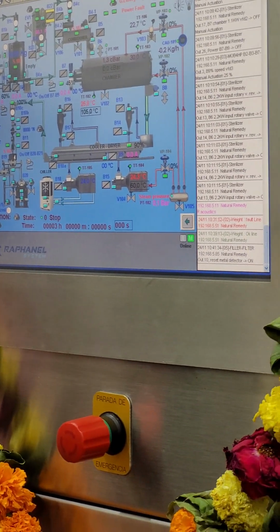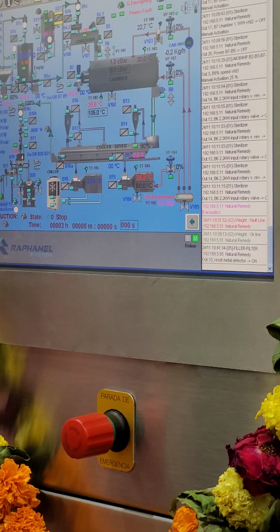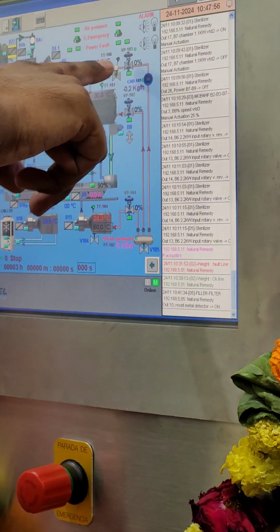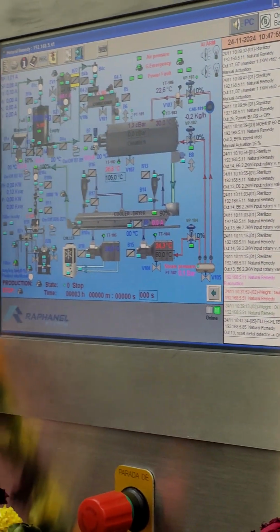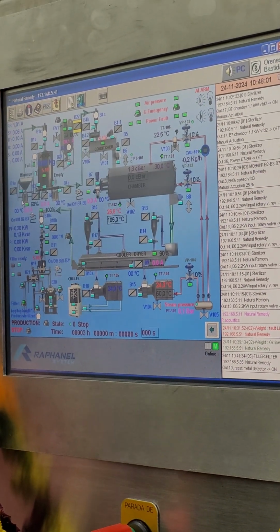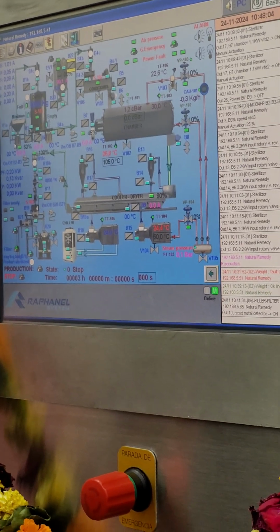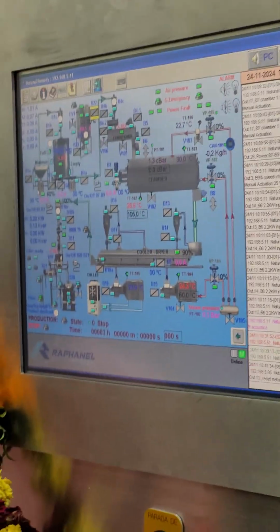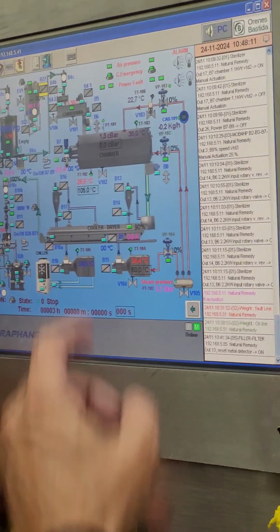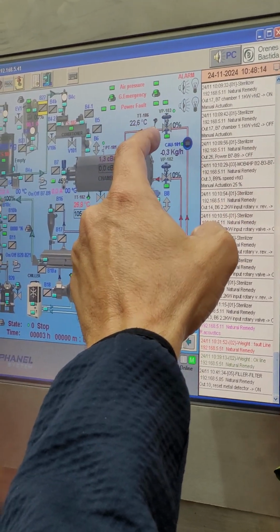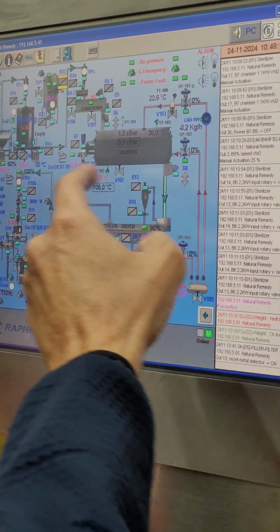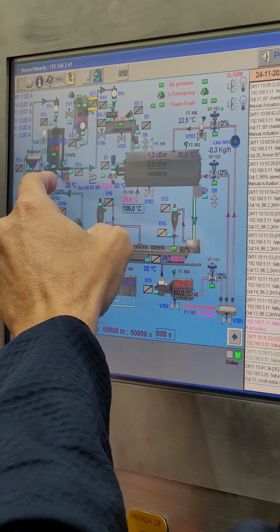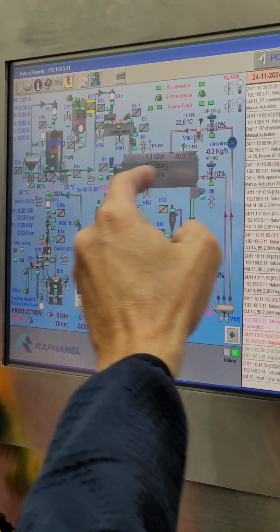Nobody can touch the doser, it's sitting there. Is any sensor there to start injecting the steam when the material reaches inside the chamber? What kind of sensor? The material detecting sensor. No. The valve knows that there is product because it knows that here you have kg of material and you have been running 5 minutes.